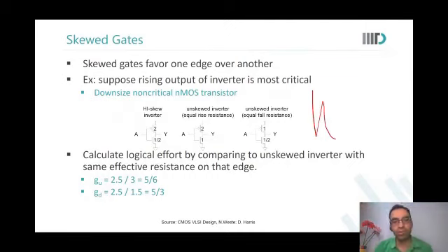So questions here. What happens when I skew? Are you able to see the benefit of skewed logic? Any questions around that? Sir, but this brings an overhead with noise margin being affected, right, sir? Yes. Even when I went to asymmetric gates, noise margin could have been impacted. But this increases the effect on noise margin to a greater extent, right, sir? Because any glitch can change the output at any instant. Yes. But for my preferred side, I get a faster output.